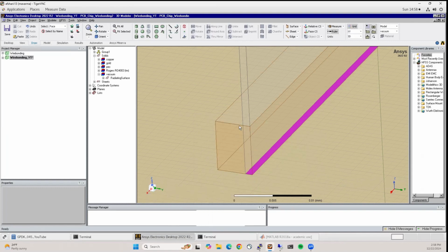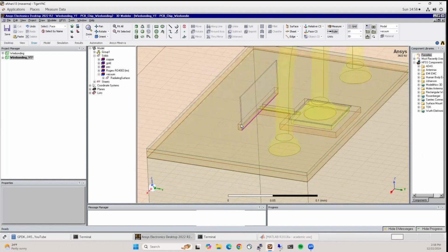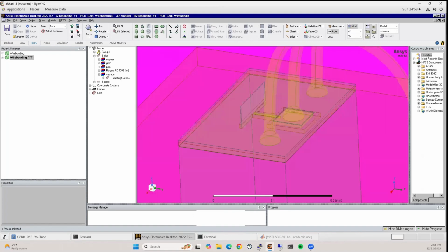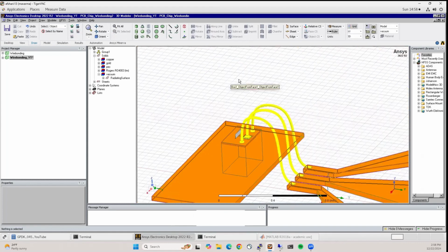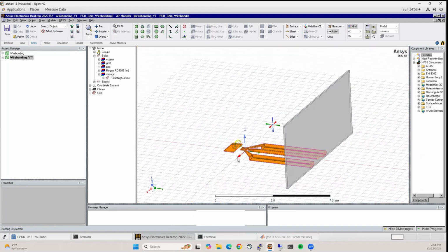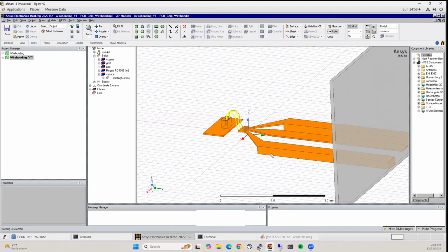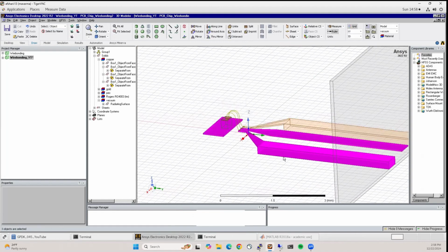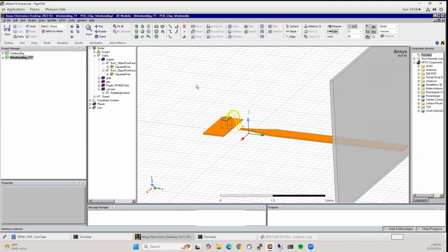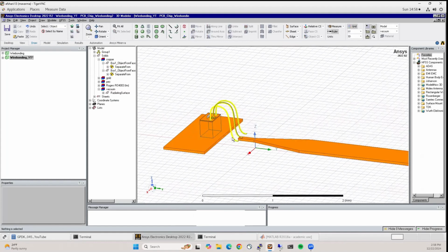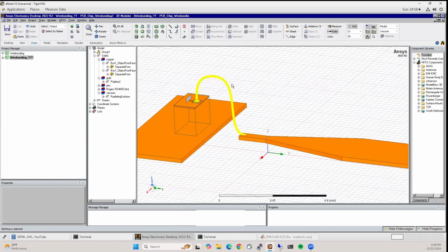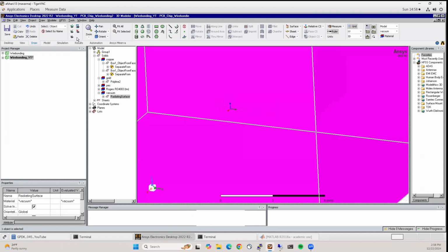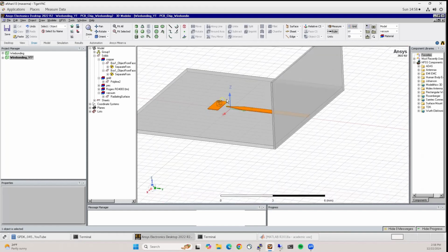Okay, so there was a gap between the wave port and the ground plane. But since the grounds were all connected, it doesn't matter much. Okay, so now that that's fixed, let's go ahead and change this model a little bit. So I only want to do it for a single wire bond. So what I'm going to do is separate these out, delete these sidelines. I'll delete these wire bonds. And let's get in there.